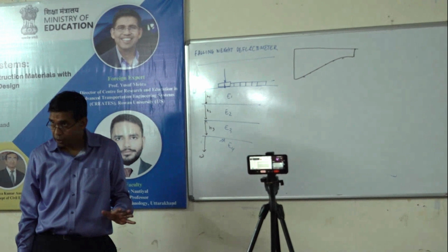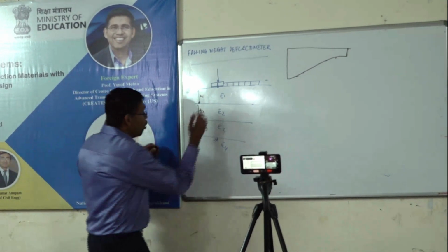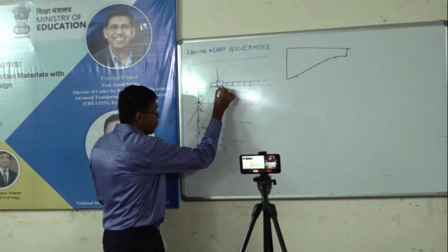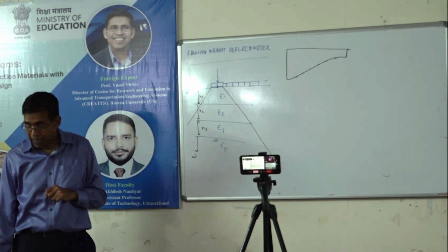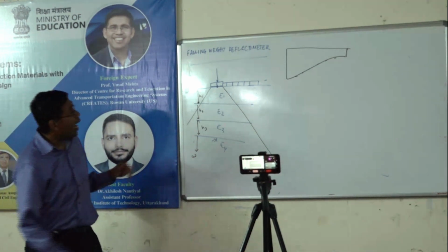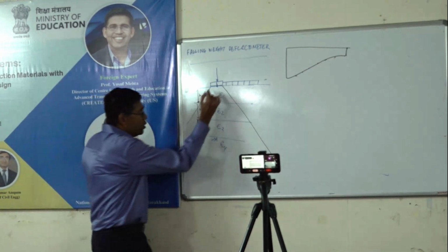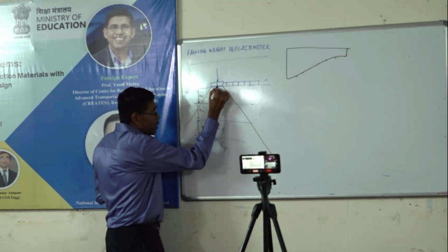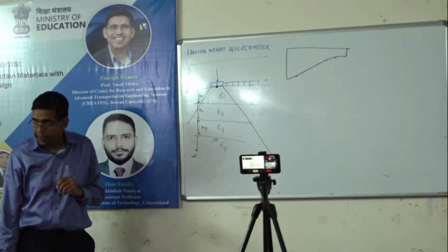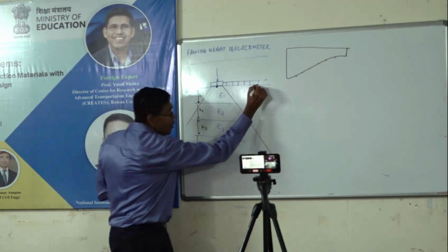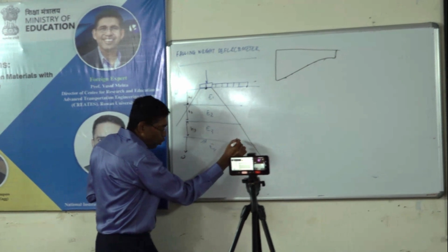Okay. Good. Now, there is a cone of distribution that we discussed several times in the last two days, correct? So when I apply the load, the deflection in the center is happening due to all the 4 layers, correct? But right here, it is happening in this particular case due to only E3 and E4.